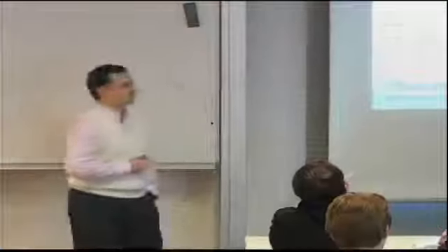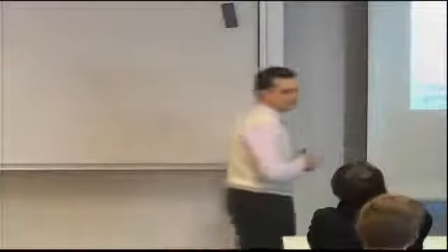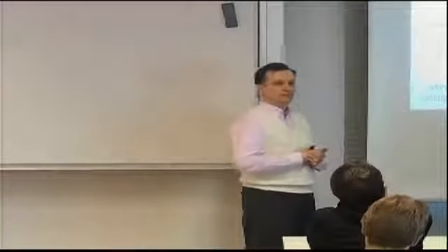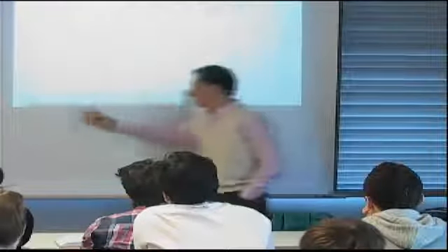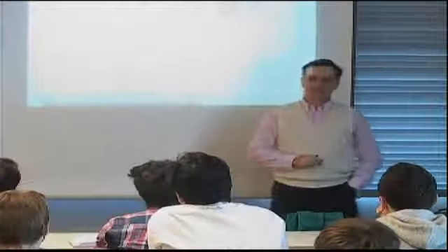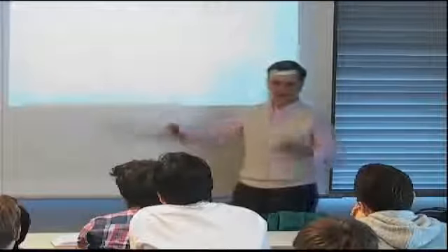Yes. The B that we are using for members 5 and 6, some part of that is underneath the stiffener. So I have this feeling that they are supported by the stiffener. If they're not buckling, that's why I said I could hopefully treat this point, because of the support, as a support to define this member as having that width and being no edge free. Basically, you are saying it's supported up to here, so somehow that should be accounted for.